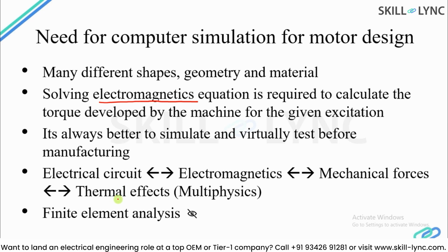So each motor is going to have some kind of losses which will result in temperature rise. These different fields of study, electrostatic, electromagnetic, mechanical and thermal, basically require a multi-physics approach for a motor design, and therefore finite element analysis is one of the methods which is preferred for computer simulation.